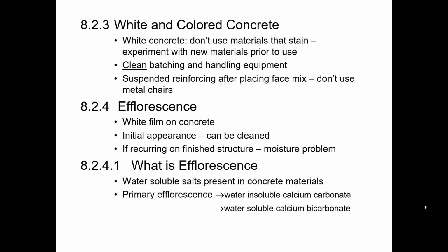So some of you may be asking, well, what is efflorescence? I've never heard of this before. Basically, it is a white film that shows up on the concrete and makes it look bad. And generally, once you see it the very first time, the very first appearance, it can be cleaned. If it keeps recurring on the finished concrete in service, it usually means you have an environmental moisture problem, where water is being continually in contact with the concrete, and it's getting into the concrete and then evaporating and making its way out. That is usually what that means.